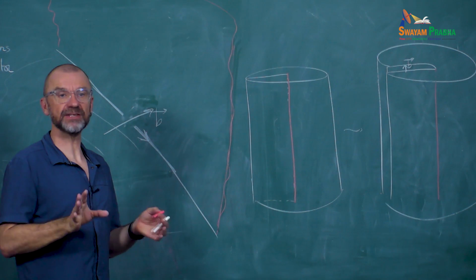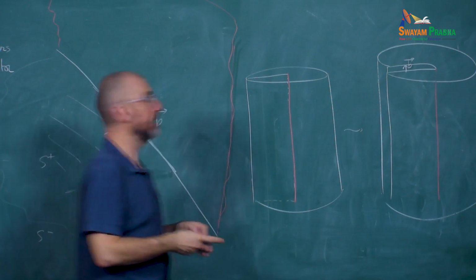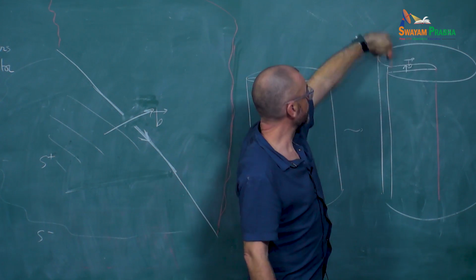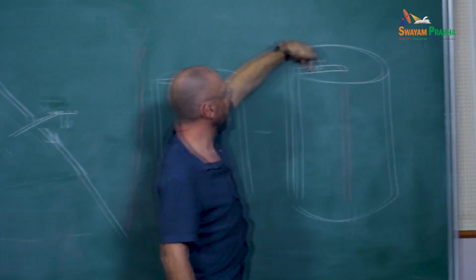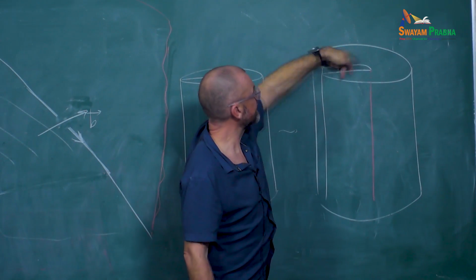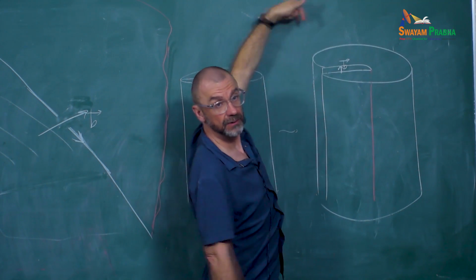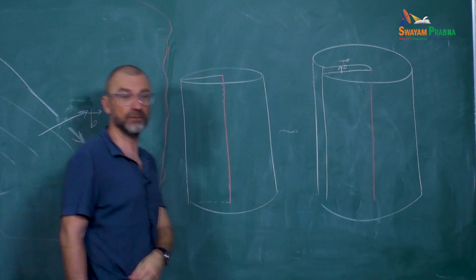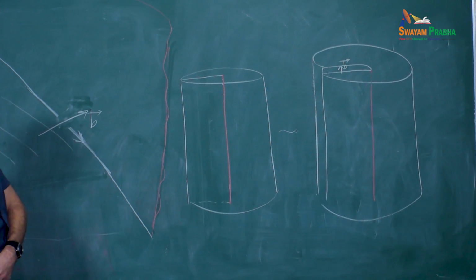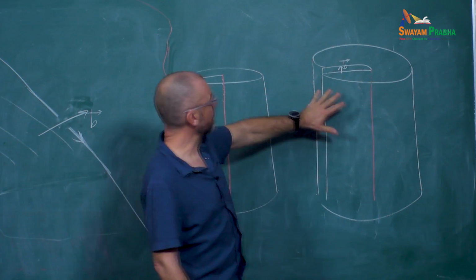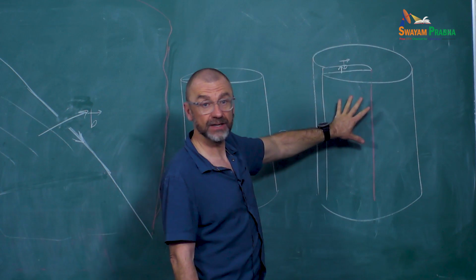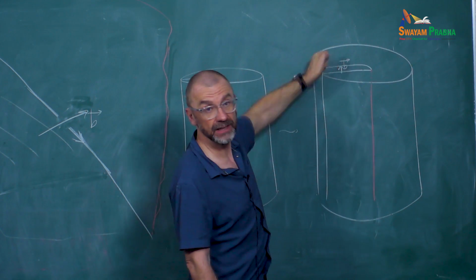That works, yeah? So that's the screw dislocation, and we were saying for the crystal growth, actually at this ledge here, if you have new atoms that come here, that will make this step just turn around the screw dislocation, and then you can have crystal growth around the dislocation. So this is a well-posed elastic problem. I want to solve Navier's equation with this jump in displacement.